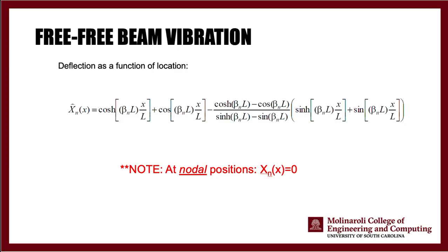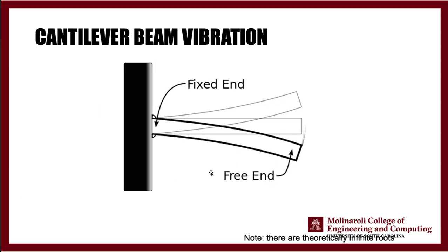The next step is to apply a different theory. So this shaker, this beam, can be divided in theory to two cantilever beams. The shaker in the middle can act as the fixed end. Again, this is not fixed, this is vibrating. So that is where the theory differs from the real experiment that you're doing. This is vibrating, this is moving in the middle, right? And has a free end. So we are dividing our beam to two cantilever beams. This is a theoretical perspective that we are applying to a real world problem.